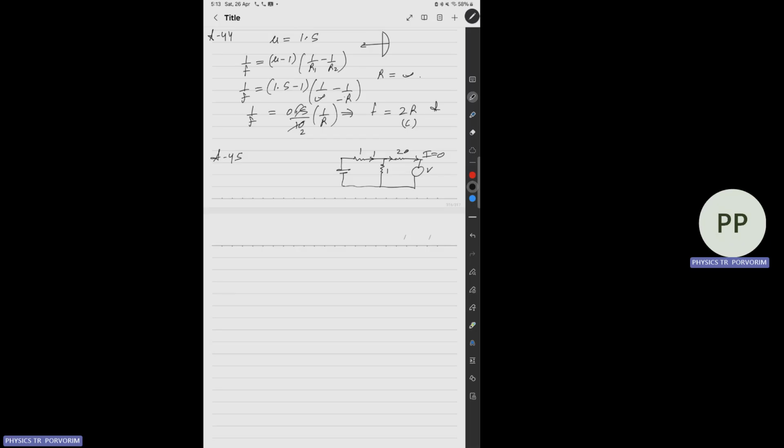So the whole current will go in this direction. So the reading of the voltmeter will be the reading across this 1 ohm resistance, because it is connected across this 1 ohm resistance. So let us calculate the current first. Current is voltage upon resistance. The voltage is 2 volt. The resistance: these both resistances are in series, so it will be 2. The current will be 1 ampere. Now we know the current, we can calculate the voltage across 1 ohm, that is current into resistance, that is 1 volt. So the voltmeter reading is 1 volt. Option A is correct.